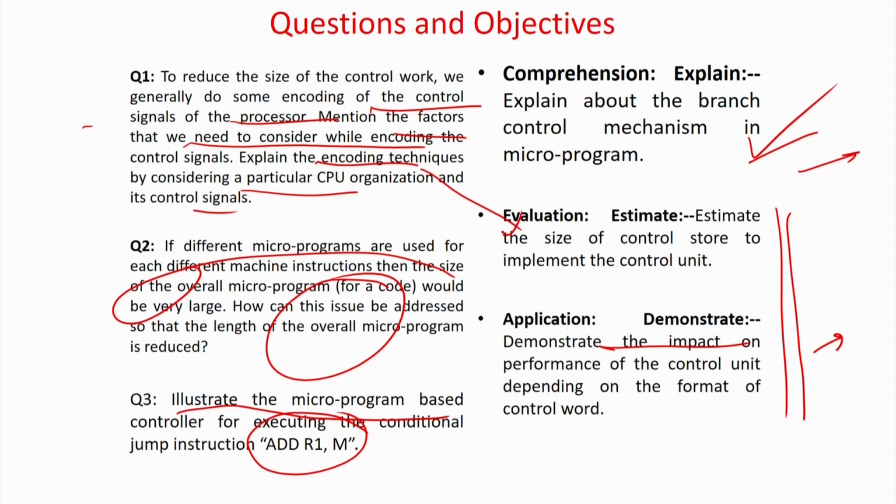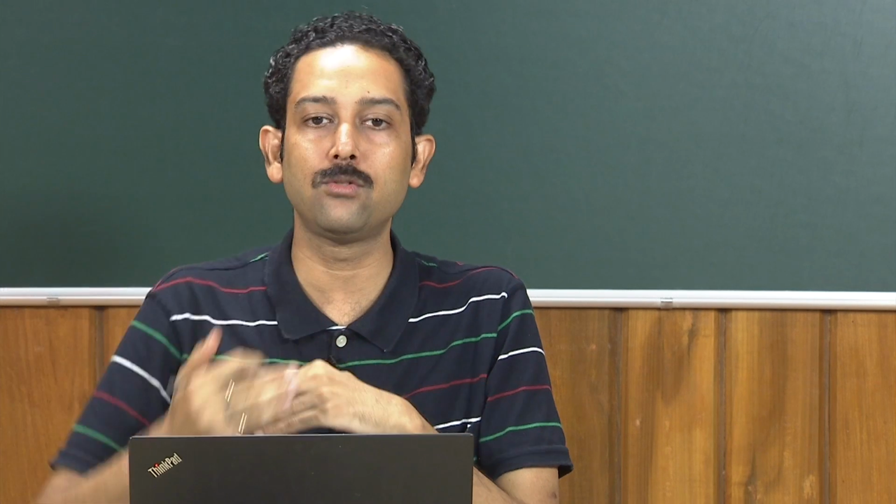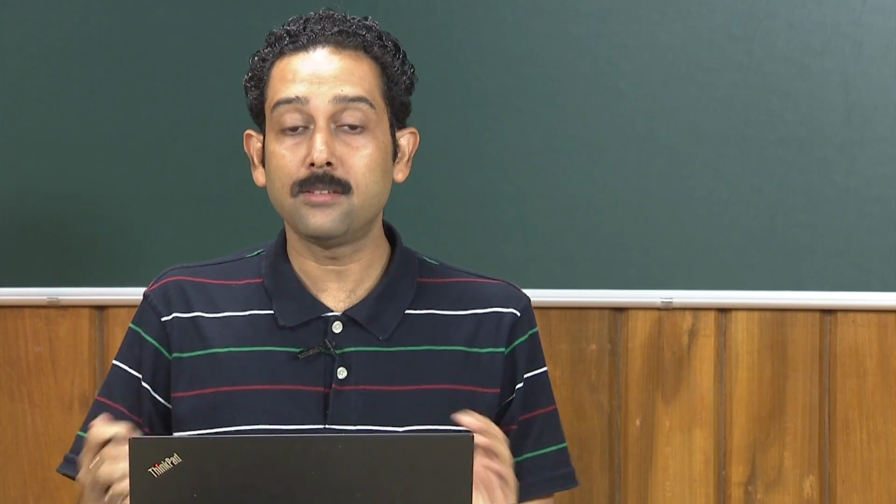and then try to see the impact of both: how many branches you require and also how many you save in both directions, both the horizontal level as well as the vertical level. Horizontal means you reduce the microprogram control memory word size, and in this case you reduce the number of instructions by merging the common micro routines for different macro instructions, right.